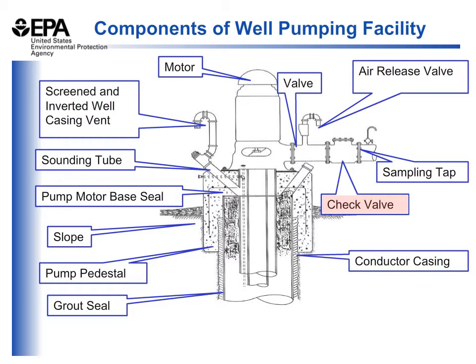well. You want to maintain pressure within the distribution system, and the check valve helps to do that by only allowing water to flow in one direction, from the well up to the distribution system. That gives you a good overview of the components of a well pumping facility.